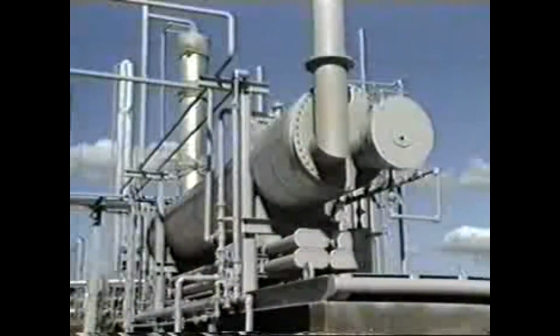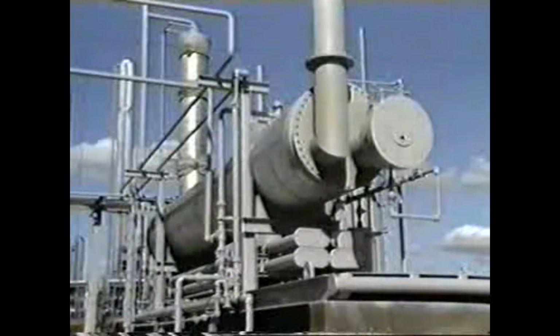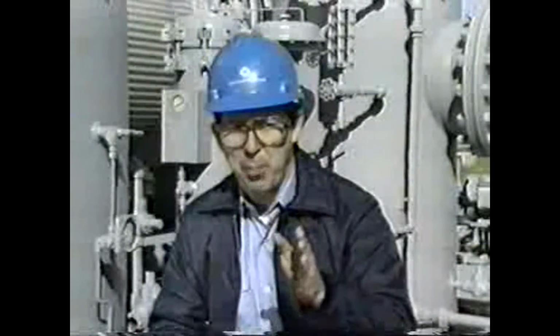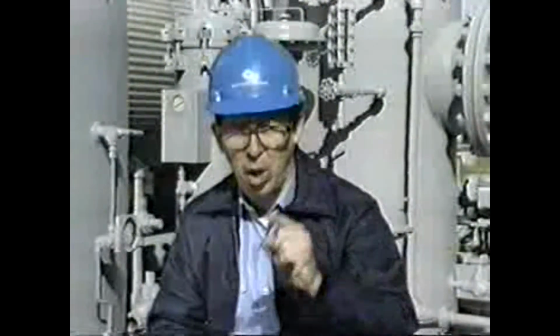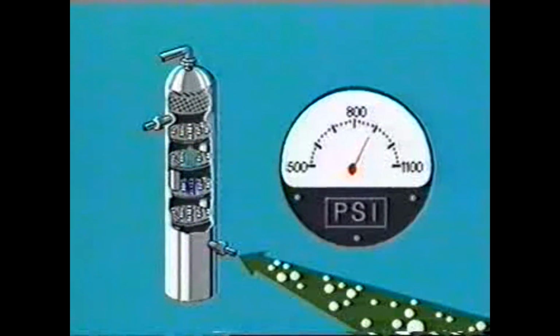Now let's look at operating pressures in the contactor, regenerator, filters, and GCG separator. If you operate the contactor below the proper design pressure, you will have problems. First, at constant temperature, water content of inlet gas increases as pressure decreases, causing the unit to work harder to dry the gas.